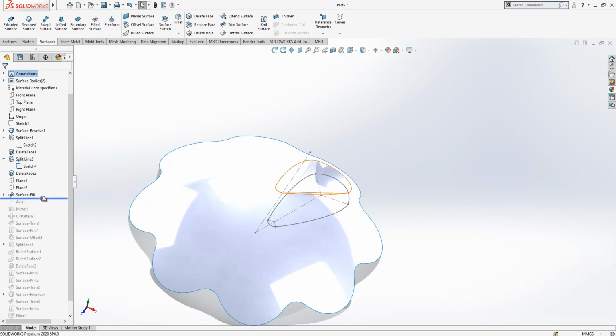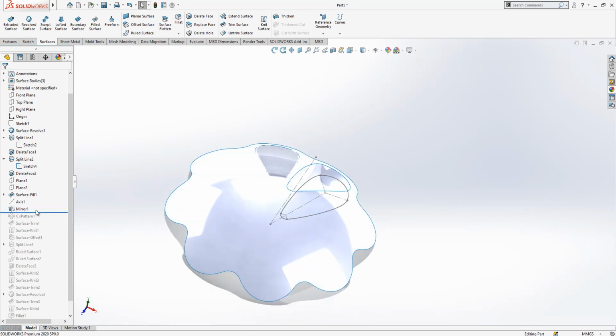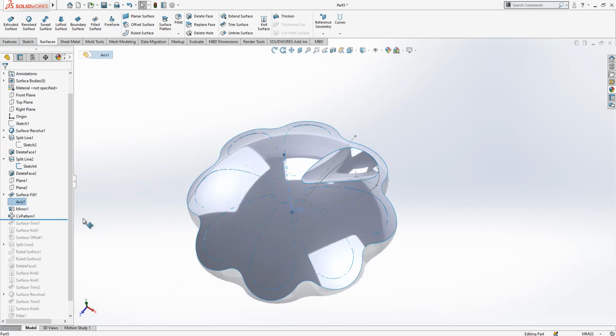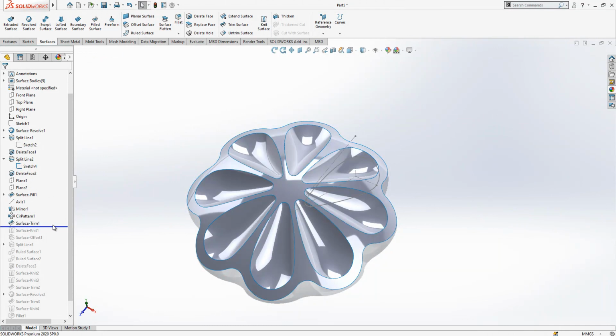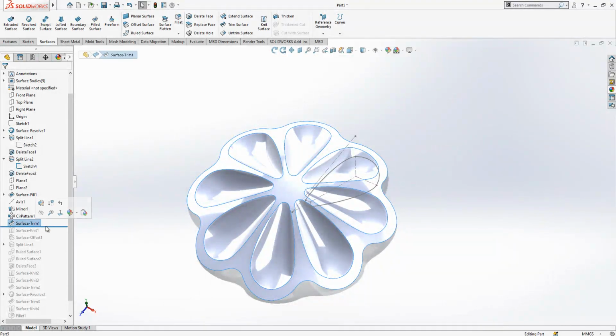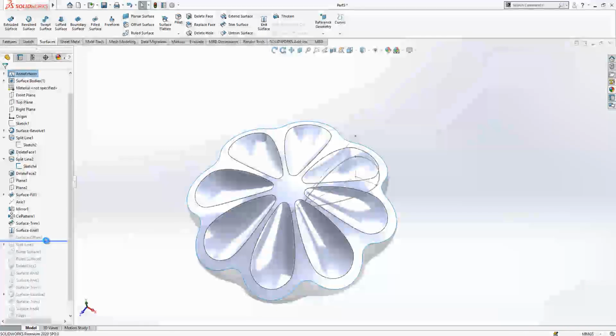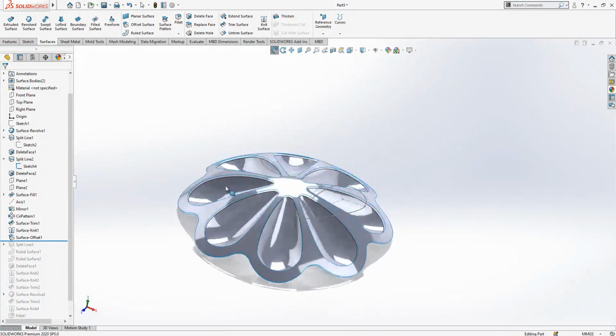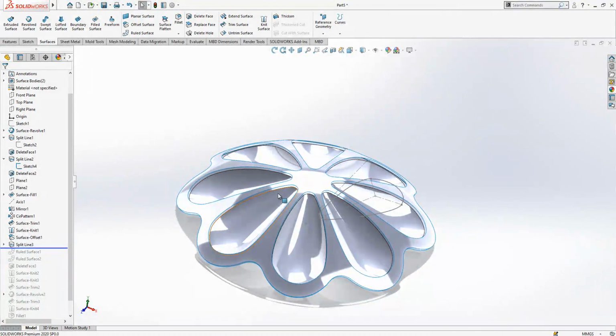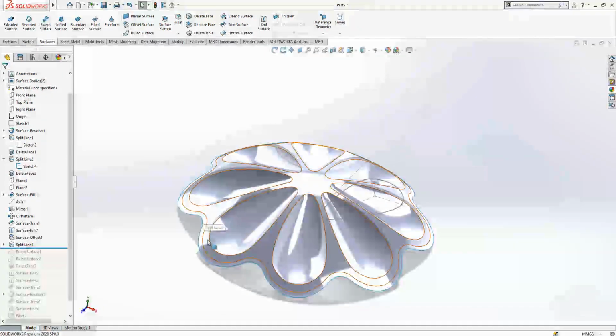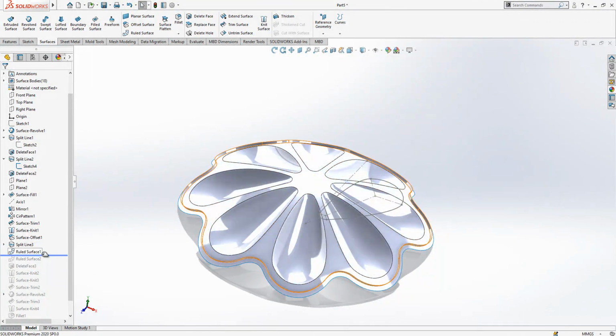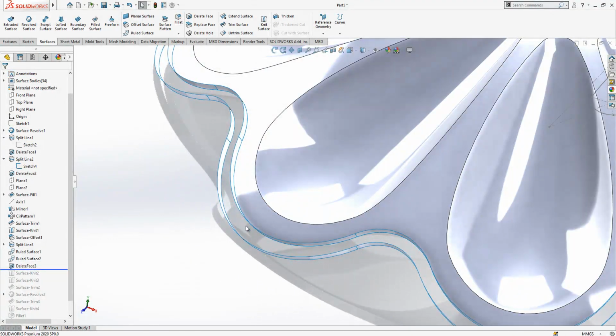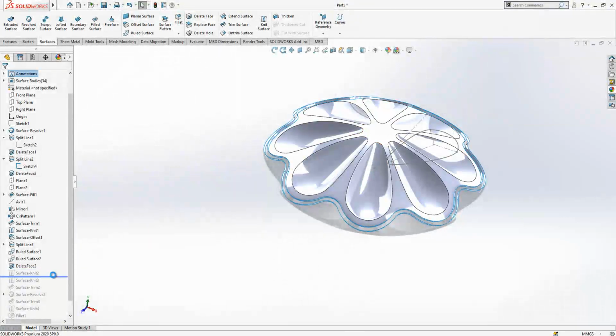And then we made a surface fill, a mirror, and then we create an axis, and we made a circular pattern and surface trims with new surface status, and then we made a knit and an offset we made here, and after this offset we break the surface secondly, and 2 real surfaces with the outer contour and a newly added surface, and then we get rid of this area which was inside, and then we knit all real surfaces.